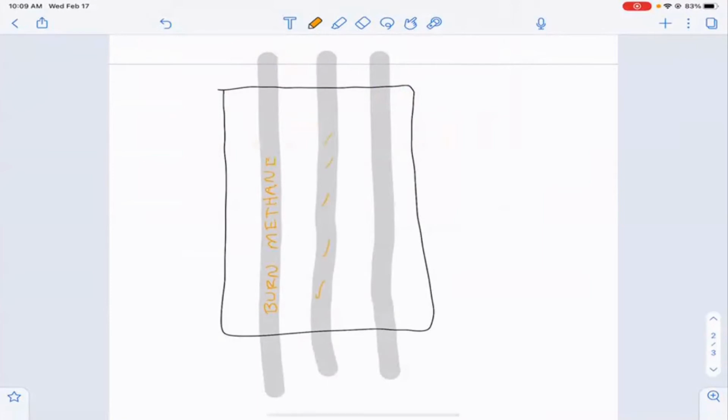So you're going to do the same thing here, and here. Essentially what you've done is, at this temperature, you've increased the surface area that's exposed to the gas phase reactants inside. So you can transfer heat faster and try to maintain either an isothermal operation or add heat at a rate that you're interested in. And so you'll exchange heat in all directions here with the inside just by burning methane.